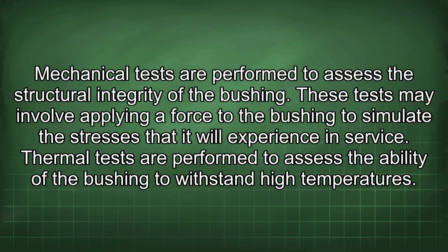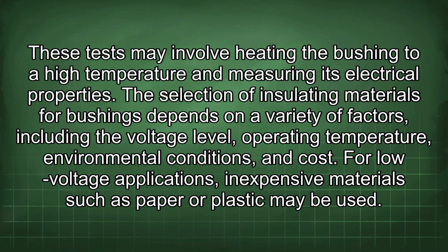Mechanical tests are performed to assess the structural integrity of the bushing. These tests may involve applying a force to the bushing to simulate the stresses that it will experience in service. Thermal tests are performed to assess the ability of the bushing to withstand high temperatures. These tests may involve heating the bushing to a high temperature and measuring its electrical properties.